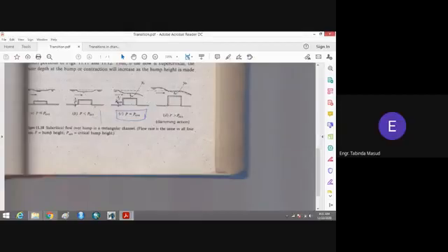At the upstream side of the weir, you can see that we have the high depth of the flow. So this is a subcritical state, and obviously on a mild slope, we always have the subcritical state of the flow. And at the downstream side, we have this supercritical state of the flow, because you can see that the depth of the flow has been reduced. So there will be a critical depth of the flow on the weir.